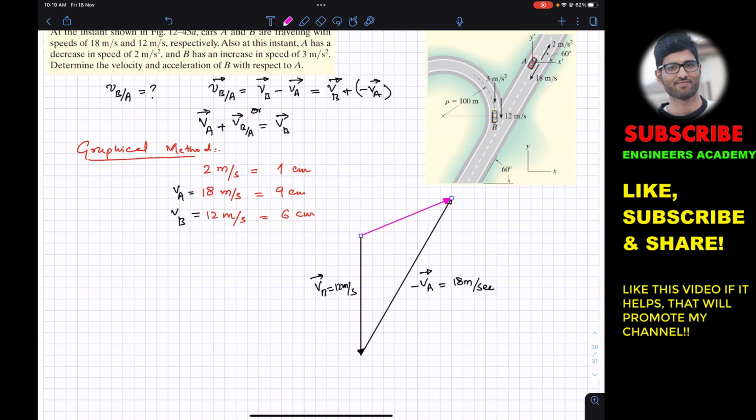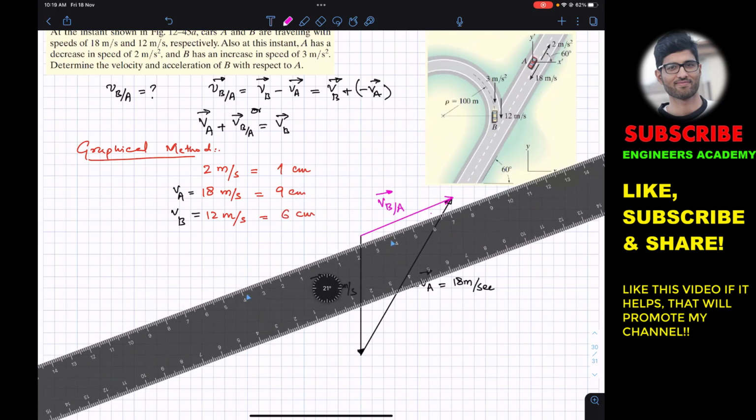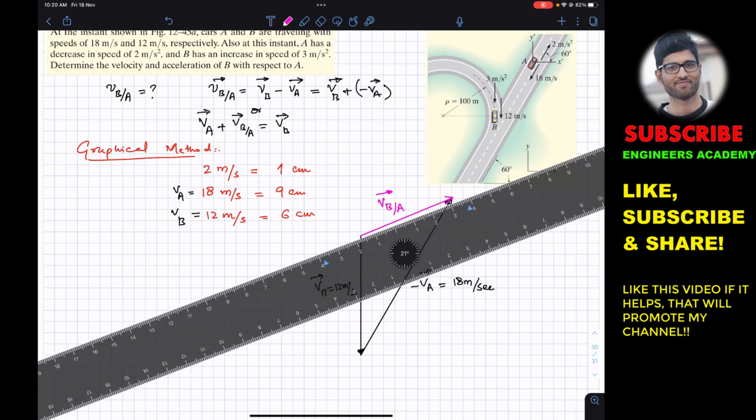Let me draw just a simple straight line. This will be our VA, VB relative to A. This is VB relative to A. And now if I take that ruler and measure the length of this VBA, that will be the direct solution.